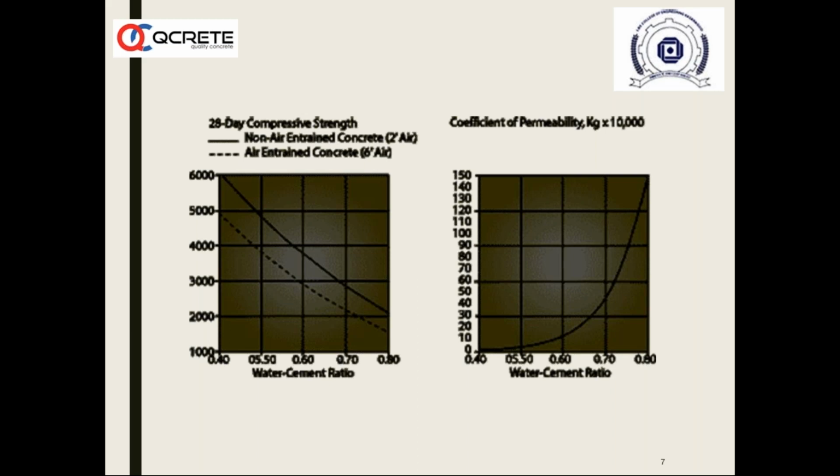That means 1 mm of corrosion attack will become 4 to 6 mm. Where is the space for 4 to 6 mm to be accommodated? There is no space in the concrete body, so it pushes the aggregates, the sand, cement and mortar, and cracks develop in the body of concrete. So it is very essential to know that you cannot increase the water cement ratio.